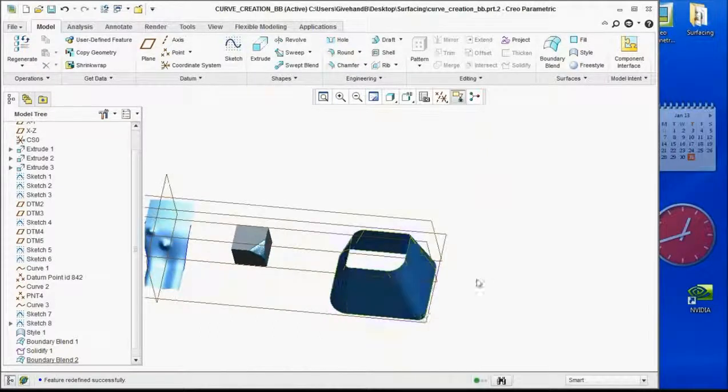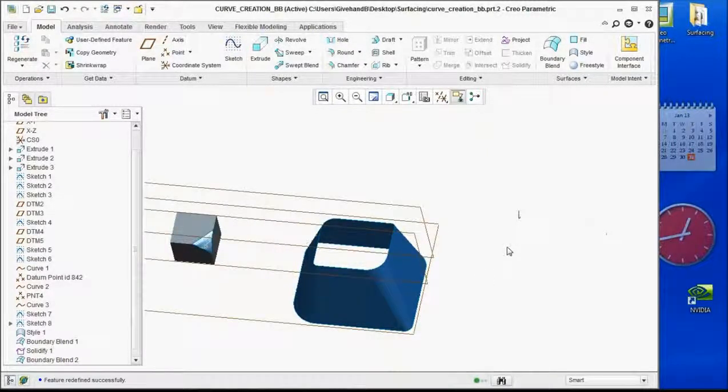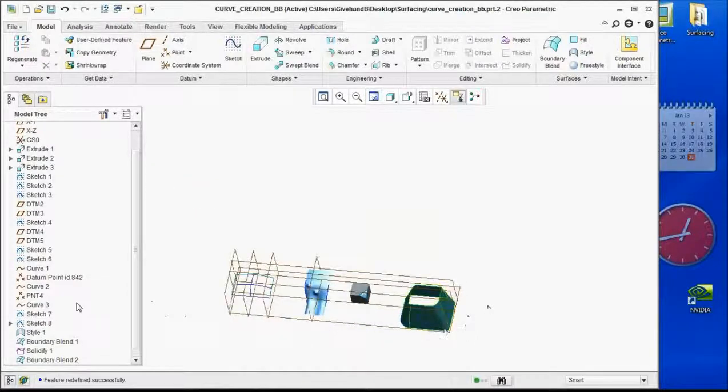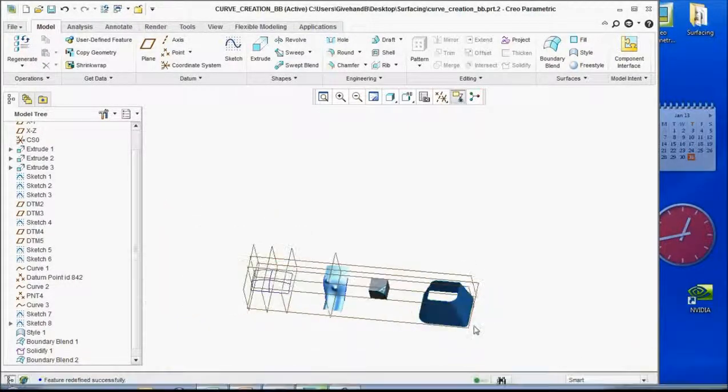I don't have an example of this, but if everybody can imagine a curve like this with a whole bunch of breakpoints and a straight line at the bottom, you could essentially drive all of this curvature into a corner if you wanted to. So all I have to do is have breakpoints up here, and in this straight curve that I have on the bottom right here, you can actually drive curvature to individual datum points if you want to, or you could break that line or that curve however many times for surface patches to match. You actually can drive curvature from natural breakpoints in the curve to datum points also if you want to, if you've never accomplished that, okay? So a few different things you can do.